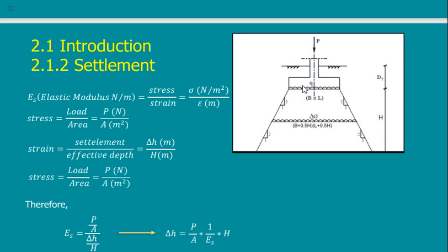As we said in many cases, if I have a foundation here, the load does not just go vertically down, it spreads. There is always a spread for the load. Because of what, by the way? It is because of shear. Because particles next to each other do not leave each other. If you are pushing, the particles below you are going to move down, but they don't move alone. Particles next to them try to help them not to go down. So as we go down, the load spreads and spreads.